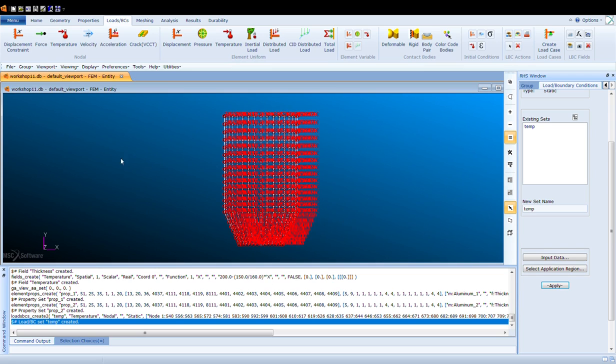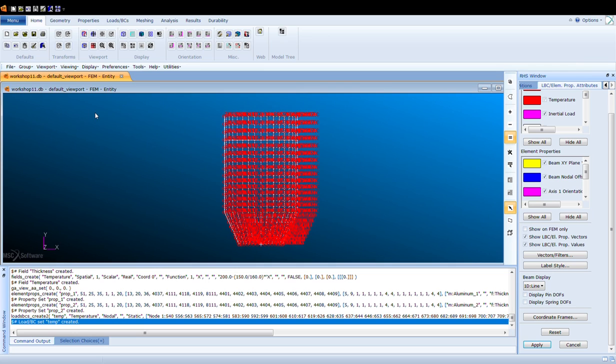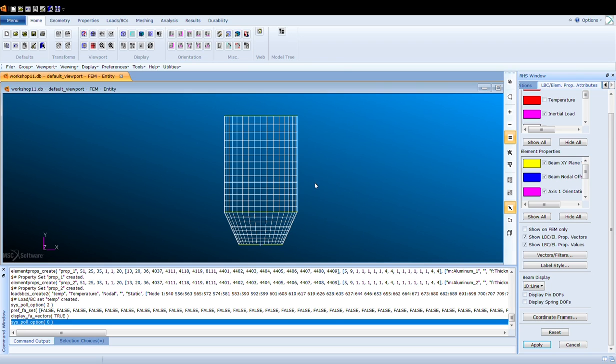A lot of temperatures appeared. They even came off from the actual, and it's kind of hard to see, so we'll just hide it. So we'll go to display, loads and properties, and here on temperature, unclick it and just hit apply. Should hide it. Once we hide it, we can proceed to the next part, which is creating a list.